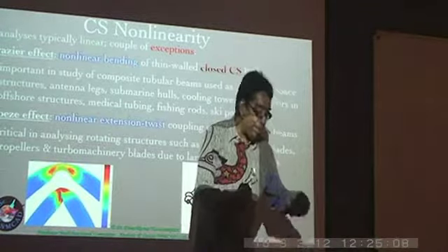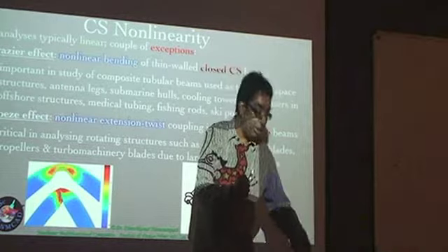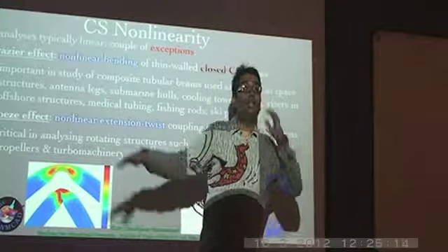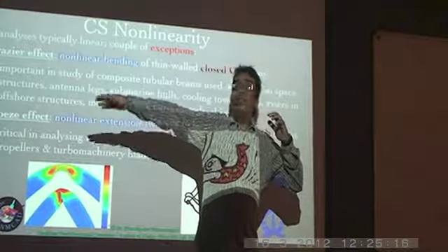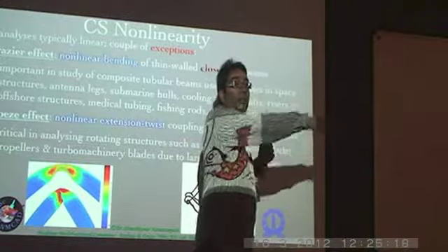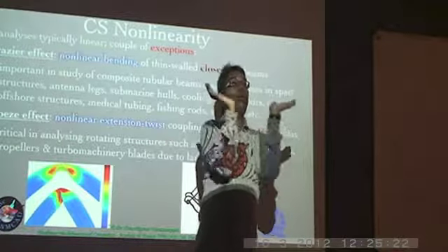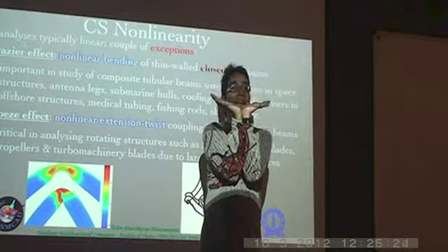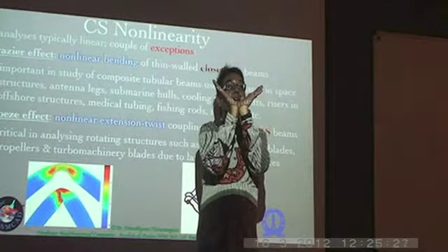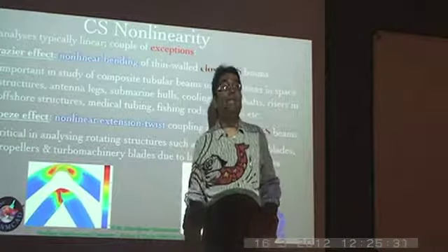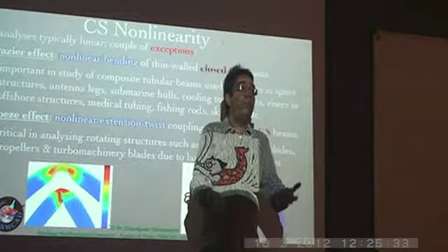For example, the simplest situation is the collective pitch. When you increase or decrease the collective pitch, all that you're doing is simultaneously changing the angles of attack of all the blades. So all the angles of attack change, and therefore the helicopter rotor plane starts coning, and it has an increased lift force, and that's what makes it climb up or down.